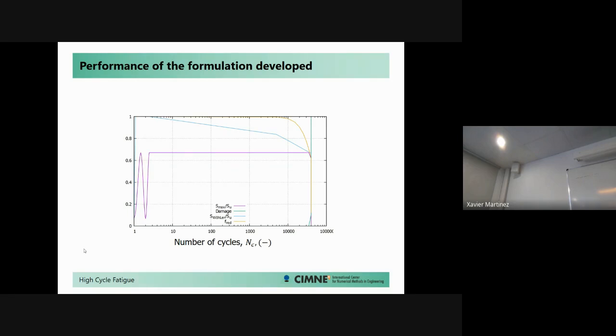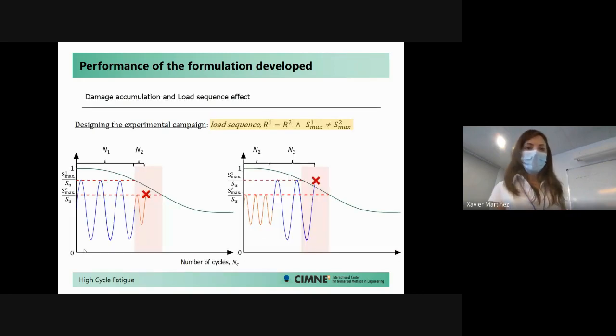Here, I was in a small increment state. Afterwards, I applied large chunks until nearly reaching the end of the elastic zone. And when I reached the intersection with the Buller curve and with the reduction function, this is when I started to accumulate damage. Because I have a very brittle behavior, with not a lot of energy available, I accumulated damage very fast, in just some cycles. So that's an idea of what I would be seeing inside the finite element simulation.